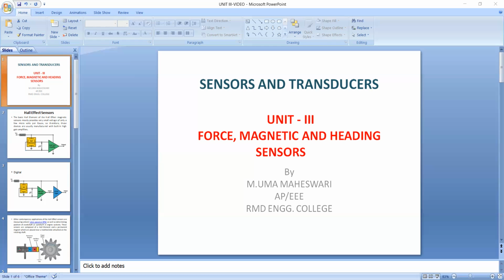The sensors are used for the measurement of displacement and detection of position of any object. Hall effect sensors may need signal conditioning circuitry, and they can be operated at 100 kilohertz. They have good immunity to environmental contaminants, and they have the ability to sustain very severe conditions, which makes Hall effect sensors widely used in many industrial applications.